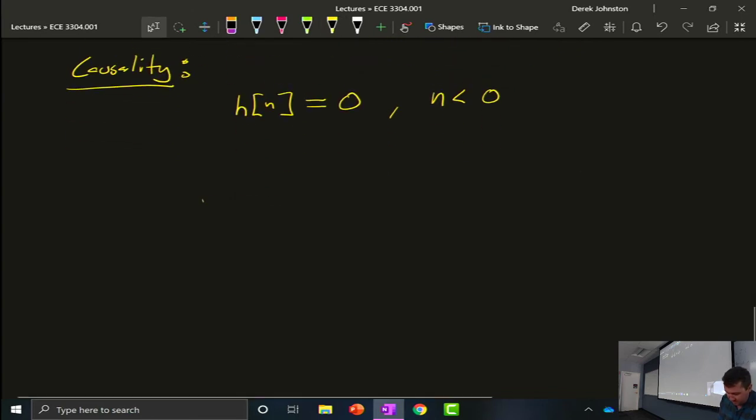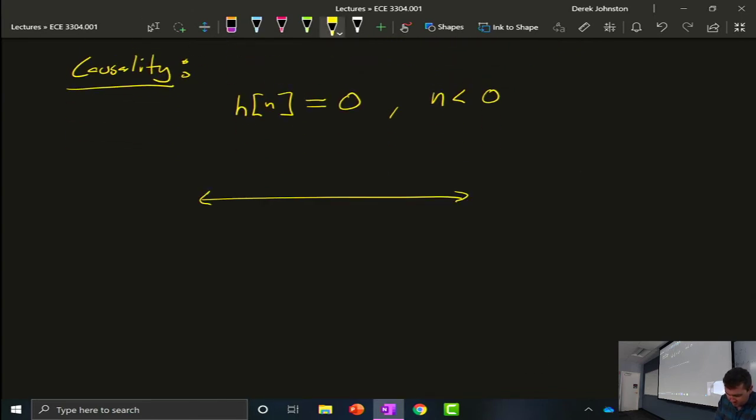So we could have an impulse response that looks like this, if that's 0, but we can't have that. That's not allowed, right? When you're designing the impulse response, your impulse response sequence has to start at 0. It can start after 0 if you want to do some weird delay stuff, but it can't happen before 0. This will be strangely important when you do your project next week. Okay.